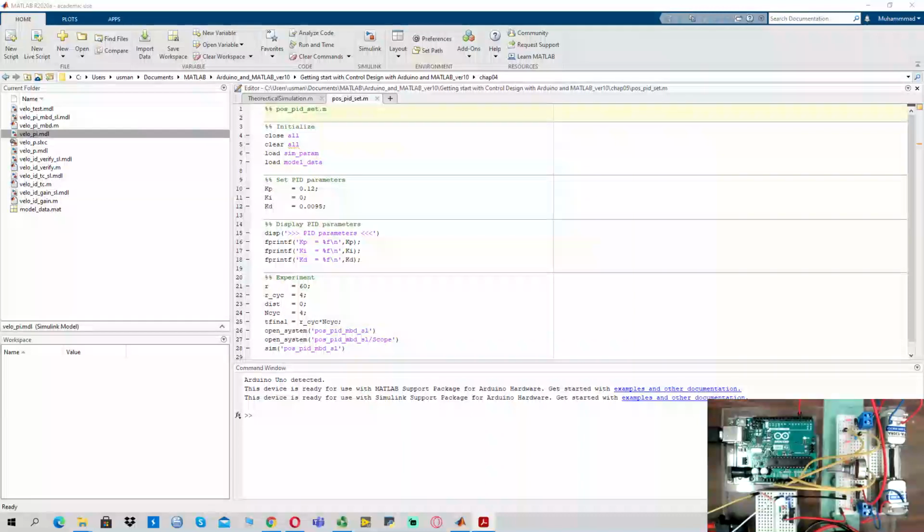Before moving forward into the presentation, you see the hardware that we are actually using, the configuration for the speed control system. For the Arduino, we are taking the analog inputs, because we have the analog output of the sensor, the tachometer, in this setup. We also have the digital output through which we generate the PWM waveforms to switch the FET amplifier to run the motor. The FET is basically responsible for driving the motor in this case.